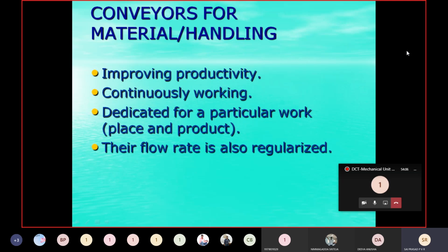As I said just now, in the municipal water treatment method, the first step is that we should do the analysis for the salt which is present in the raw water. Based on that, we are supposed to dose it. Means, how we are dosing it, quantities are there, but how are you going to add to the conveyor belt? So the RPM of the conveyor belts is very important. If they move very fast, more amount of chemicals are dumped into the mixing tank. It is a bad thing. If they move slowly, then what will happen? Then again, the process of cleaning will not be completed. So the RPM of the conveyor belt is decided by the design engineer based on the input raw material. Input raw material is what? The hardness of the raw water which we are supposed to treat.